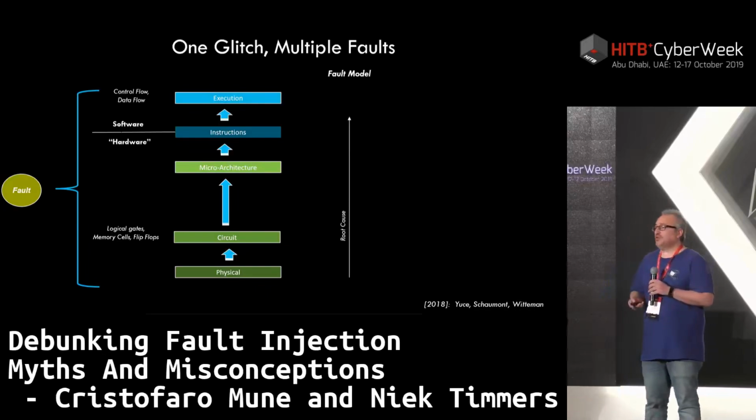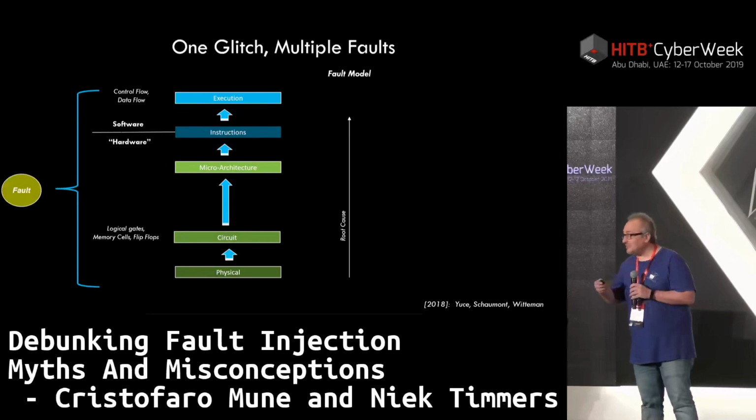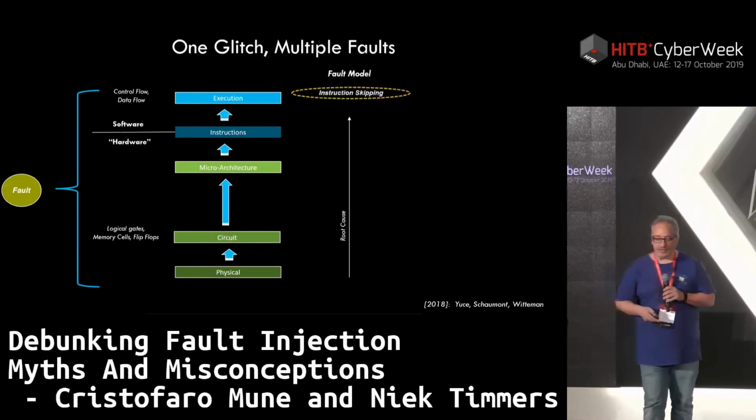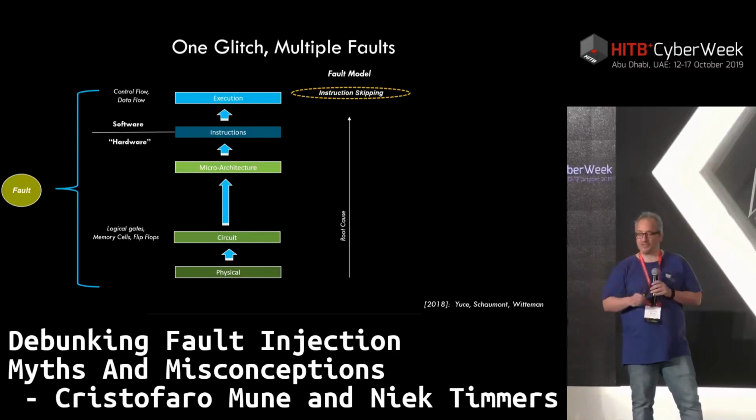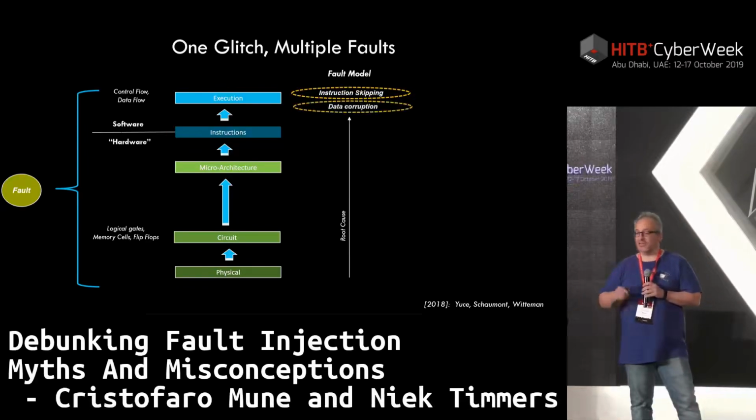So regardless of where the root cause is, this stack of faults arrives at the point where they become visible to you, or the point where they become interesting for you. Usually these have been modeled as instruction skipping, so we can skip this instruction, or as data corruption. Maybe we can flip this bit in the state. This is the usual thinking.